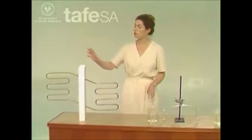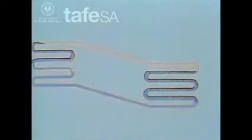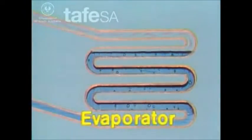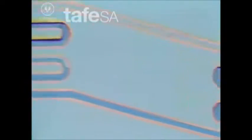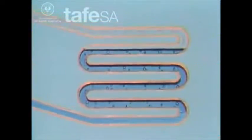Changes in pressure or temperature directly affect the saturation point. If we were to imagine a situation where we wanted to transfer heat from a hot space to a cold space, then a simple closed system like this would do the trick. Refrigerant absorbs latent heat and boils in the heat exchange unit called an evaporator. The vapor travels to the other coil, the condenser, and gives up latent heat as it condenses. The liquid then returns to the first coil and the cycle continues.